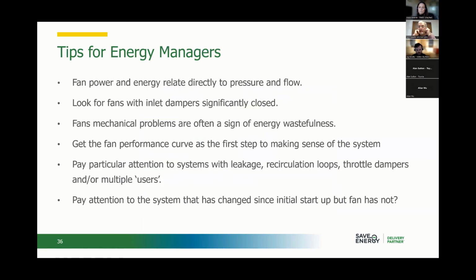Tips for energy managers. Okay, so this will kind of summarize a few different things I've said so far. Fan power and energy relate directly to pressure and flow. Remember, pressure times flow divided by efficiency and time. All those four things have virtually identical impact in terms of how much energy you have or how much energy you could reduce it by.